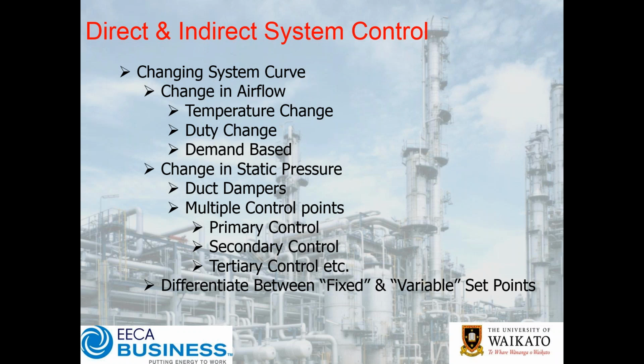Now, what's often useful from time to time when you're looking at a system, there may be a number of those points that have been set and forgotten about, and they may no longer be appropriate given other systems that have changed or been tweaked or modified. And so it is useful from time to time to go back and review and ask the question, does that system need to be retweaked, retuned, or is that actually still appropriate? Plenty of instances where a lot of those secondary and tertiary control points can actually be eliminated very carefully, which can do wonders for a system's performance.